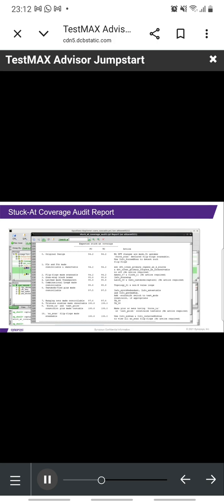The last couple of categories in the report can only be addressed with the insertion of test points to increase the number of faults that are ATPG testable. The most important value of this report is that test points are used as a last resort to increase coverage. Since this analysis can be run on RTL prior to code freeze, many testability issues that impact optimal ATPG coverage and ATPG efficiency can be identified early on. This has a big impact on the last-minute ECOs to address testability.